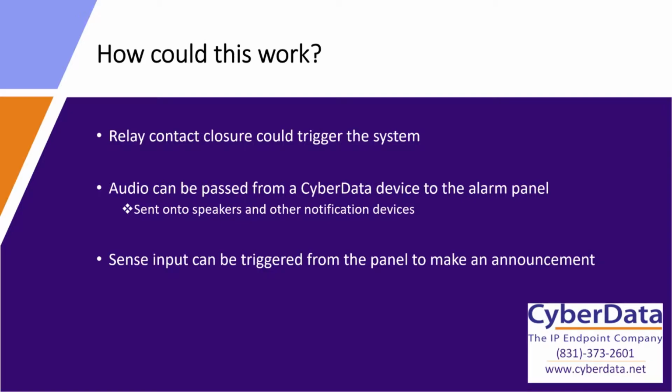But it can also work in a couple different fashions, where if you get a little bit smarter of an amplifier, this is something that we're encountering a little bit more often now, really with more modern fire control panel systems, especially with universities, where they've actually got almost notification systems actually built into the fire panel system, where it's not just used in the event of an emergency. It can actually power speakers and make general announcements. So audio can actually be passed through from one of our devices into that fire alarm panel, and then thus onto all of the other speakers. And it can be used for just general announcements, but it could also be used for emergency announcements.